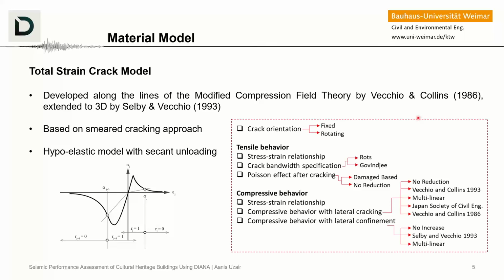The stress in this case is defined with hypoelasticity, where the loading and unloading behavior is along the same stress-strain path. But the user manual for Diana says that in the current version, the behavior in loading and unloading is modeled differently, with secant unloading, which you can see here, and it is controlled by the factor alpha.